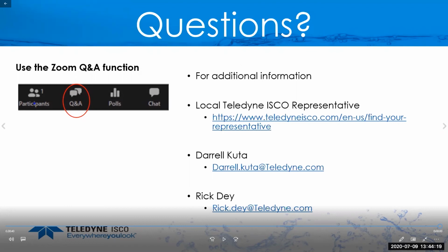Yeah, thanks, Rick. Then there's another question along those same lines. Someone was asking if you need to install aerators on applications with a smooth surface to create some surface turbulence. I have seen that before on other technologies, where they needed an aerator to create surface turbulence to be able to get a velocity reading. But with the laser flow sensor, no. In that particular application in Canada, they were able to turn off the aeration, and the laser was able to penetrate subsurface and read the actual velocity.